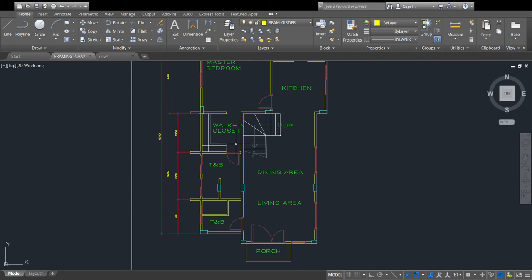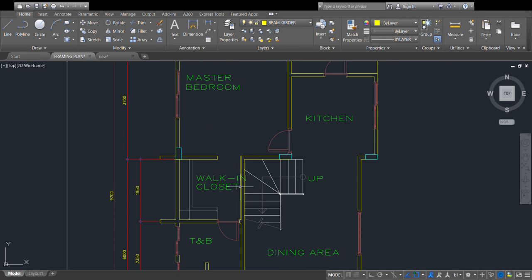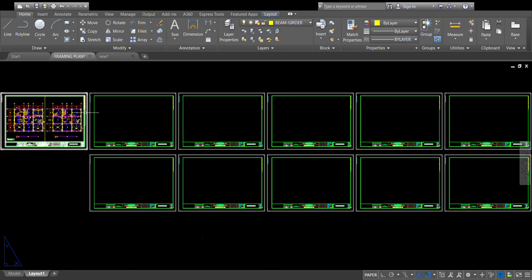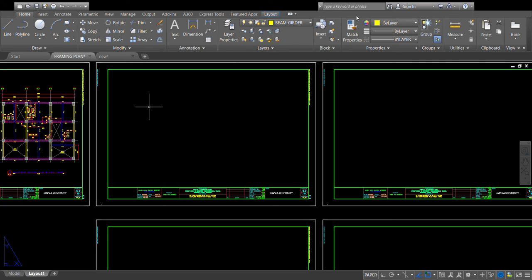Okay, so this is one of your drawings. My question is, if you're going to print it, if you're going to put it in a layout, what will this be? Listen, layout. Click layout view. Okay. Now, look for the term MV. MV is short for multi-view. Okay. Press MV.